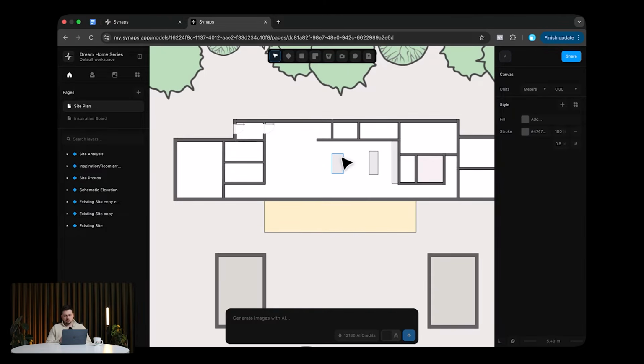Okay, so with that said, the next step is, let me add the room. This would be the room tool. Basically once you click in a closed space inside the walls, it will tag them. It will measure the area inside of it, and then we can also add hatches or textures inside of it. So I'm going to do this for each and every one of them. This is going to help with labeling everything. It will make it quite clean actually. So let's just add this. Let's go here, room. Let's just add this.